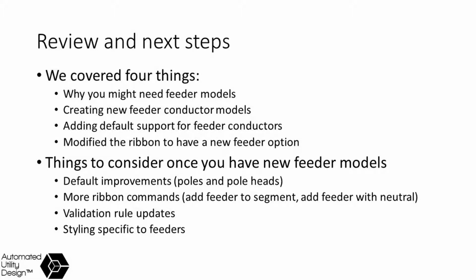Let's review what we covered. First, I talked about why you might need to have feeder conductors models in your AUD configuration. We then looked at the steps required to add new models to the list of available conductor models and the model attributes that define a conductor as a feeder. We then created the new feeder models. We used the SPS Smart tools for editing models in Excel and creating 3 new conductor models with the conductor type set to feeder conductor. These new models were loaded into AUD.